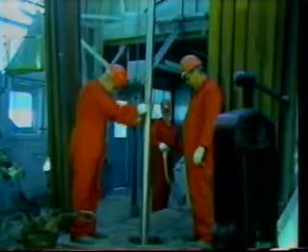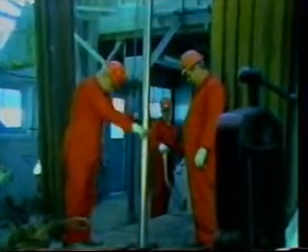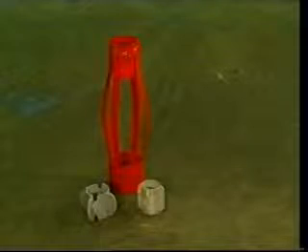Care must be exercised so that no damage is induced while running the screens through the BOPs, wellheads, and other equipment. Since a screen may need to be replaced, its size should allow washover operations to be conducted. The screen installation should also include centralizers that can be washed over. Centralizers are usually spaced about 15 feet apart.